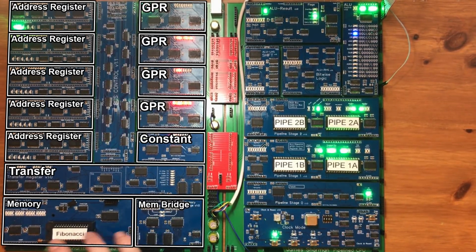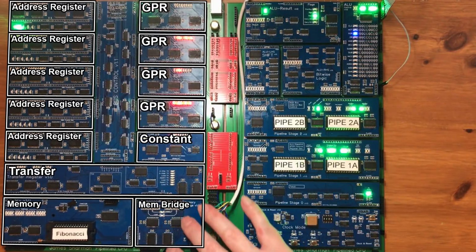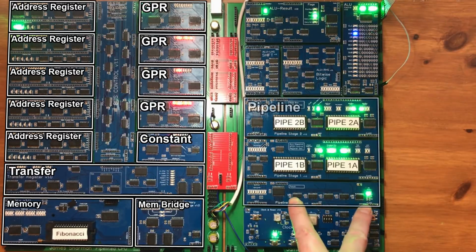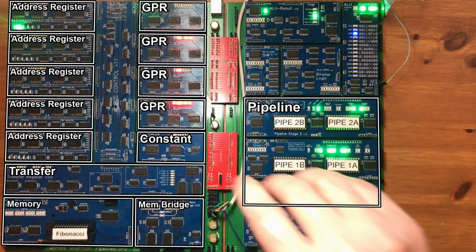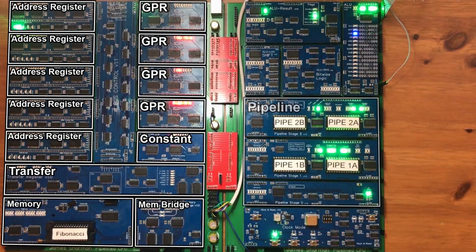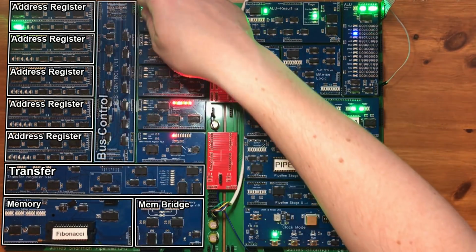So it basically allows memory to read and write on the main bus so it can be transferred to and from registers. That's because the memory is not hardwired to the main bus as it is in some simple processor architectures, because I've got a second channel that allows the memory to be accessed by the fetch unit over here at the bottom of the pipeline, so that the fetch unit can read instructions while the main bus is being used for something else. And that's one of the properties that gives this processor just a little bit of extra speed capability.